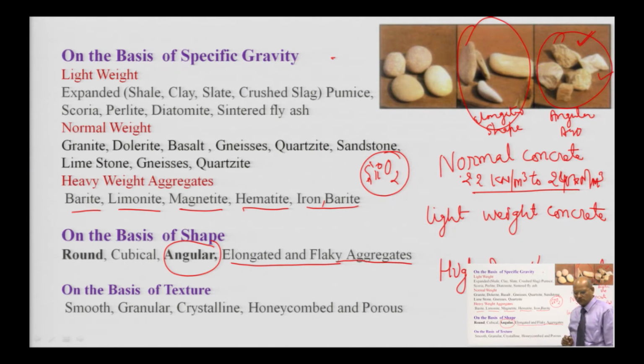We do not have proper experimentation on how to measure the bond strength of cement paste and aggregate, but bond is very important. If the interface of aggregate and cement does not have a proper bond, then there will be a reduction in the strength of the concrete.